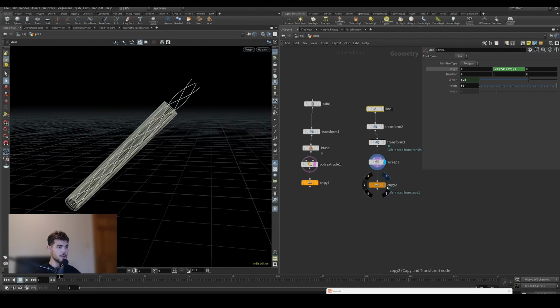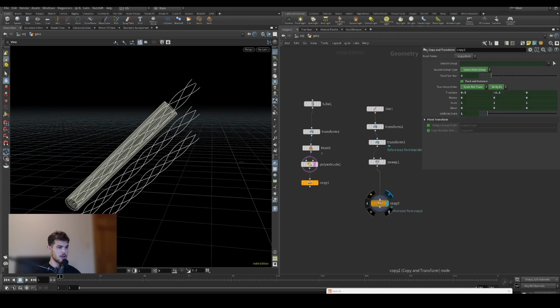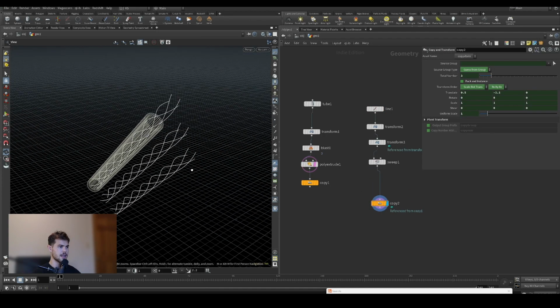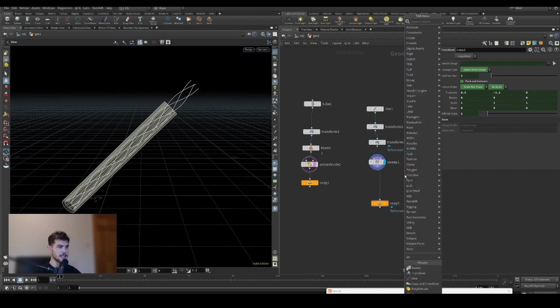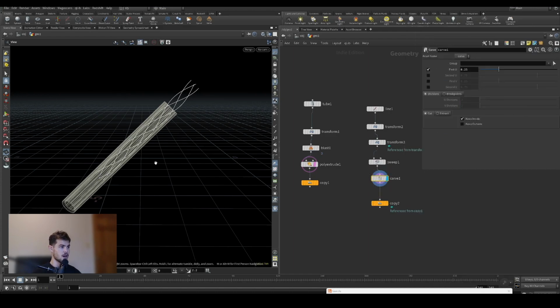So then we can copy that to, or actually, I think again we're going to do maybe a couple more steps before that. So next, what we want to do is use a carve. So the carve will cut off a section of the curve for you. As you can see, this one's going from the start to the end, where we need to use the second U so that we can go from the beginning to the end of the curve.